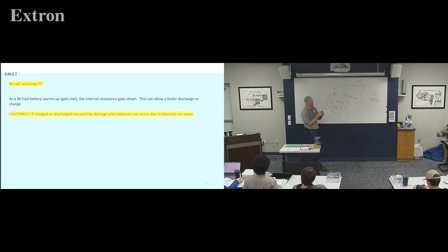The reason I show you that little step is when the FAA asks some questions, they can throw you off a little bit with the math. You'd always want to base your amperage on, obviously, the voltage when the thing's operating, right? Not when it's just sitting at rest. That's only step one though.